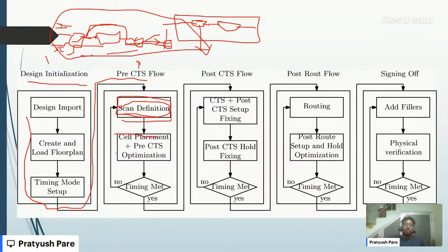And okay, cell placement and pre-CTS optimization, then we do the timing, and if it is not met, again do everything. So for timing now, since we have put in scan also, for scan also we need to do the timing, okay.